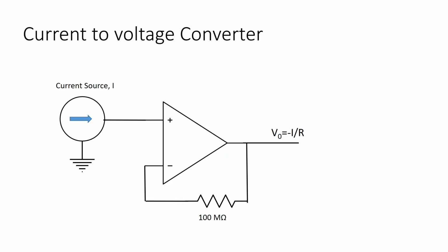Alright, we're now going to turn to the final topic in this Hints for Lab Rats, and this is low amplitude signals. So this here is a schematic for a current to voltage converter. So for example, I used to build scanning tunneling microscopes, and they looked like a current source here. Anyway, anything that's a current source, which could be, for example, a photo detector, which will generate a current when light hits it, generates some number of picoamps, which is a number of picocoulombs per second going into this terminal